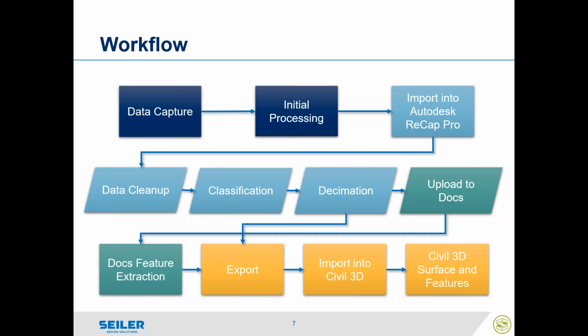Okay, it was a way to basically layer out your point clouds into points. Now we actually have the ability to follow the standard ASPRS classifications, at least the first dozen of them: point class 2 ground, class 0 unclassified, never classified, class 5 buildings, etc. So that ability is in there. They have also introduced a semi-automated ground classification utility into ReCap Pro.